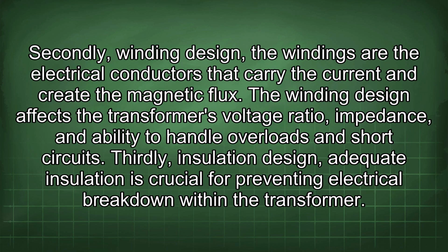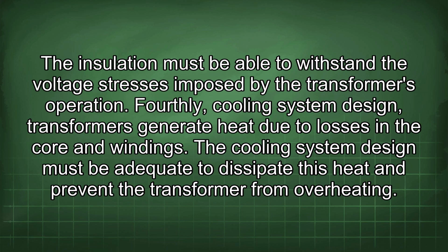Secondly, winding design. The windings are the electrical conductors that carry the current and create the magnetic flux. The winding design affects the transformer's voltage ratio, impedance, and ability to handle overloads and short circuits. Thirdly, insulation design. Adequate insulation is crucial for preventing electrical breakdown within the transformer. The insulation must be able to withstand the voltage stresses imposed by the transformer's operation.